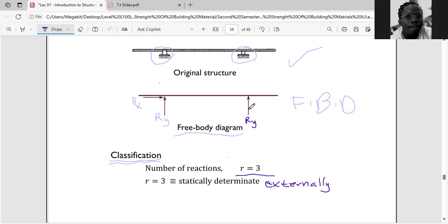In cases where you encounter fixed support, you also have to remember that it has three reactions. We said the first reaction moves towards the east side, the second reaction moves towards the north side, and the third reaction becomes a moment. In some cases it may be an anti-clockwise movement, in some cases a clockwise movement. The nature of the question would determine that.